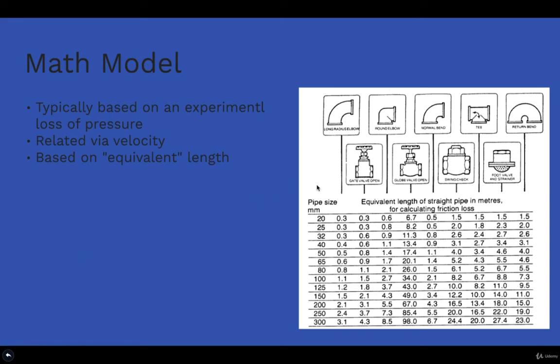Do we model fittings? Well, you will require the specific data on your fittings. Whenever you buy a new fitting, for instance, this long radius elbow, this gate valve, or maybe this return valve and so on, the specification must come from the operator or from the brand you're buying it from. So whenever you buy it, you can use their tables, or you can also make your own.